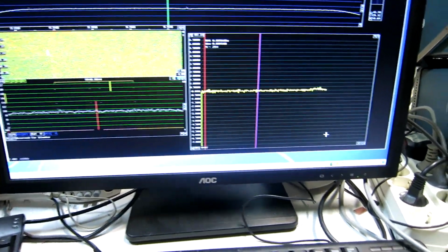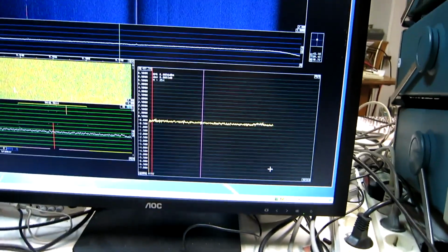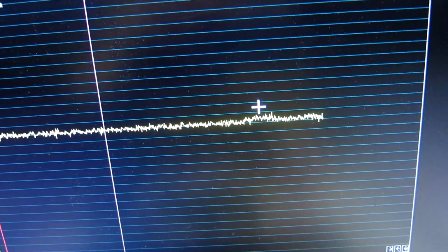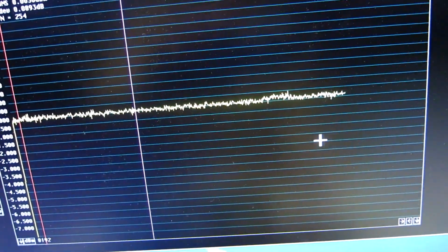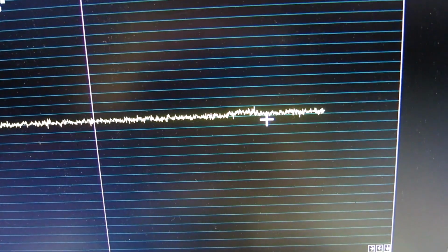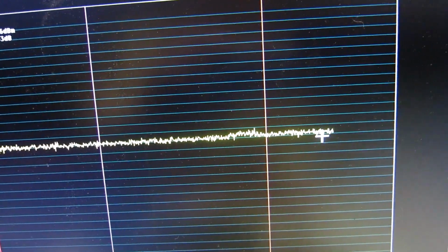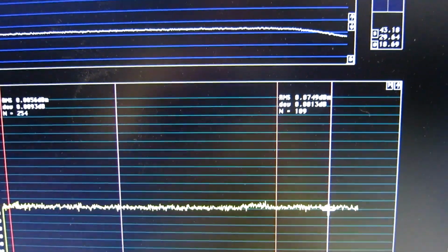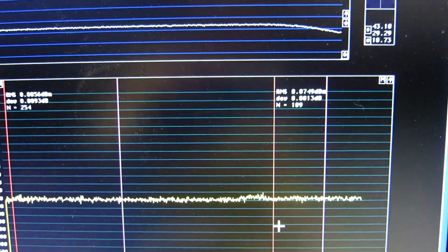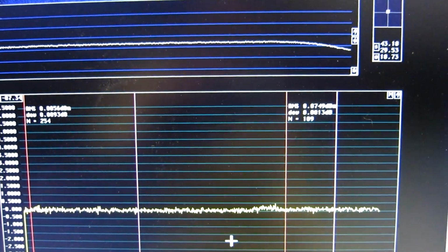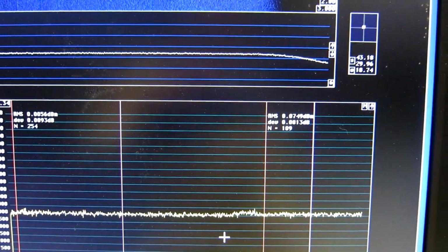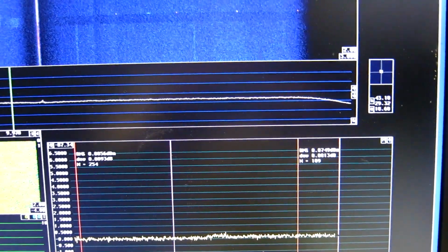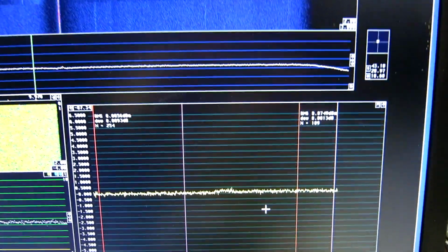There was a noise increase when I had nothing connected at this point, but I wait for a while to see the temperature of the 50 ohm here, and it shows me that the noise from the junction FETs is in the order of 0.07 dB. Very small indeed. But I don't need a notch filter, I will do this without it.